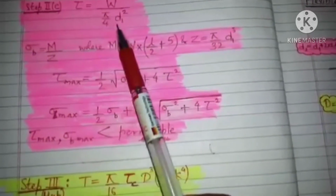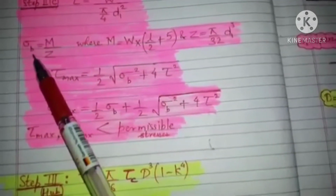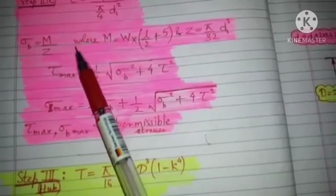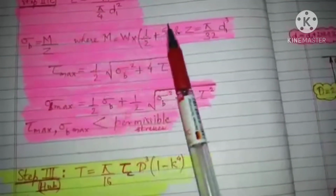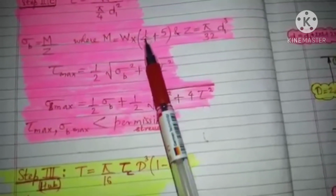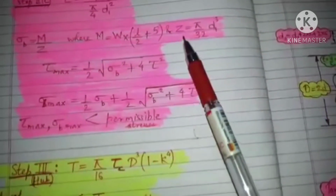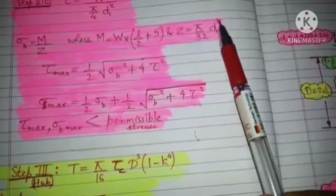With that we have the direct shear stress. Then we need to find the bending stress on the pin, which is equal to M upon Z. We can find M with the formula M is equal to W into (L divided by 2 plus 5), where we know W and L. Then we have to find Z, which is equal to pi by 32 d1 cube.